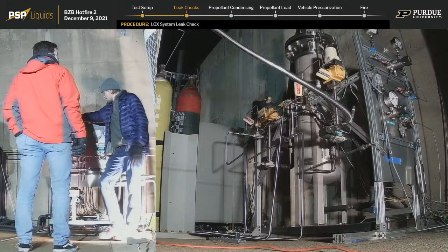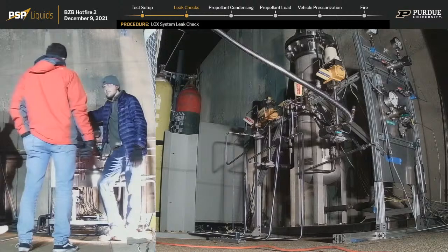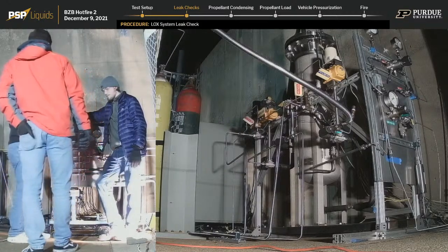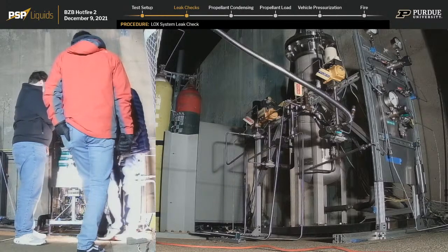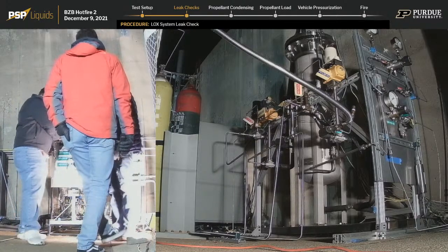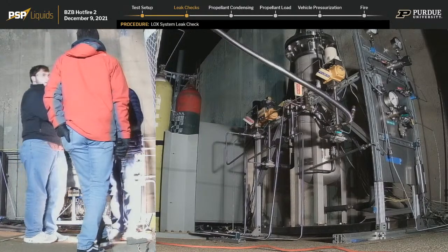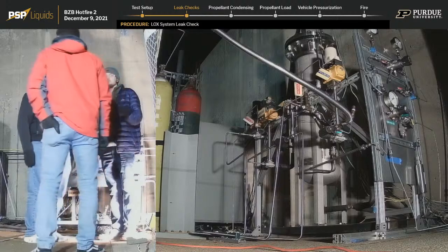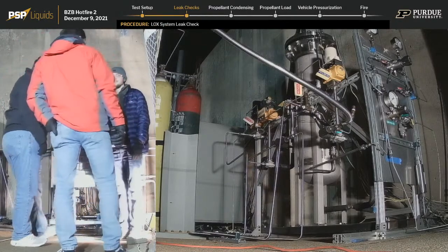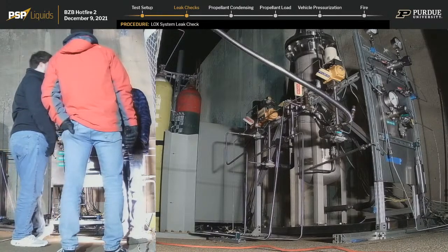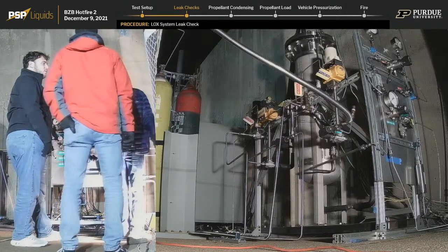This can result in losses of pressure or fluid leaking out into the courtyard, which are undesirable outcomes for a hot fire. It seems like we would have leak checked this entire thing beforehand. Do new leaks spring up between each operation? If they are left for a certain amount of time and changes are made to the system, leaks can appear. So it is important after a prolonged period of time without any kind of test to perform leak rate checks again and adjust accordingly. Got it. And this is very critical for the LOX system, to make sure we aren't leaking, because LOX is very nasty to work with.